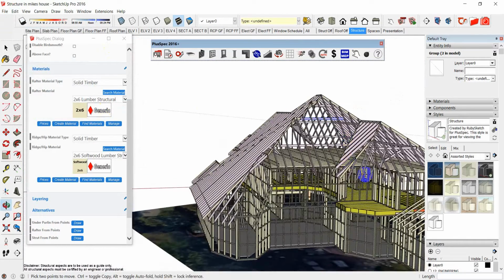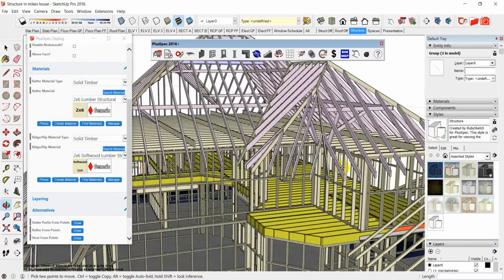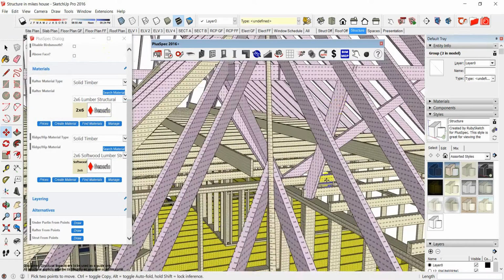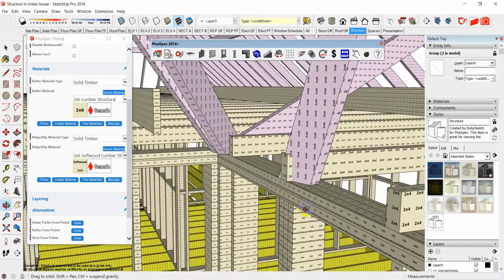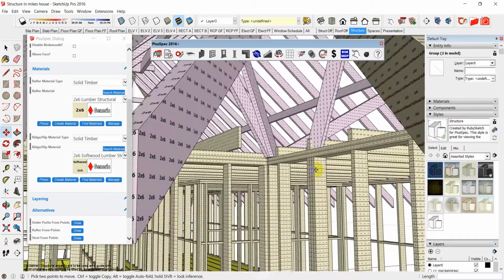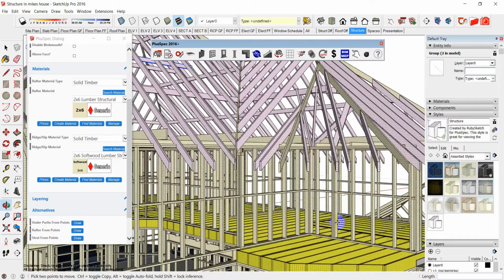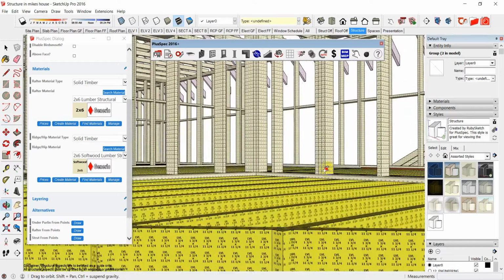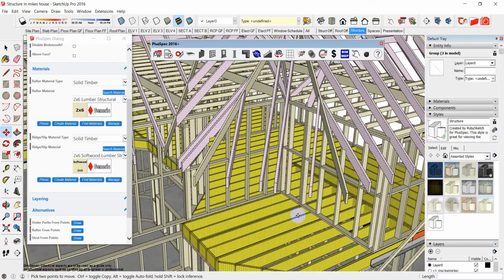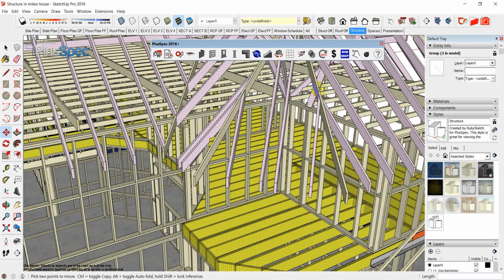Okay. And here's a good example of a load path. You can see I have a strut there that's holding up, and that strut is going over top of a cluster of studs, which I actually did manually, and I'll show you how I did that in a second. And then it goes down to a joist, and that joist is free spanning from 2 walls. So I doubled the joist up, and what I would do in this case is, I'm not sure whether this is all going to work, and I'm really just trying to get a bill of quantities here. So I might go in and put a tag in.